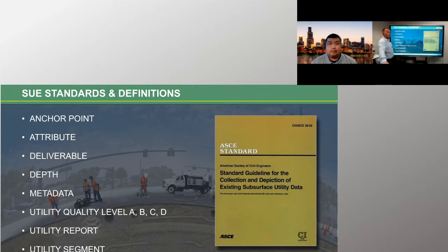Depth, and I know our previous speaker, Compass Data Incorporated, you mentioned depth. There was a question about depth. This is the difference in elevation, obviously. I'm probably speaking to a lot of surveyors in the room. It is a difference in elevation between the top of the utility segment and a reference point that is anchored on a datum, such as a DTM, surface grade, absolute elevation, or benchmark elevation.